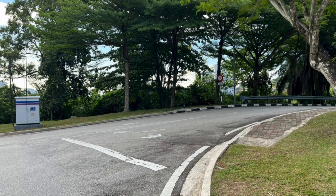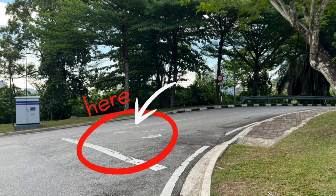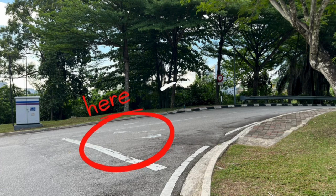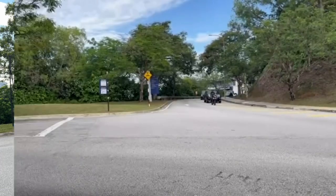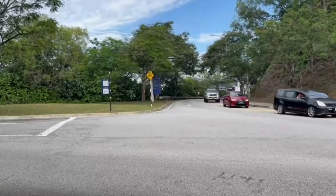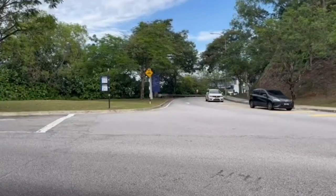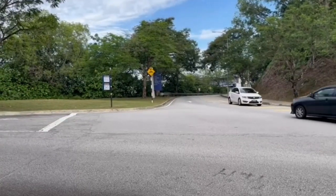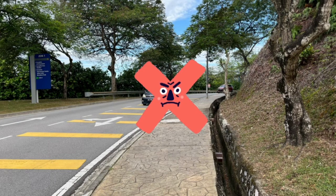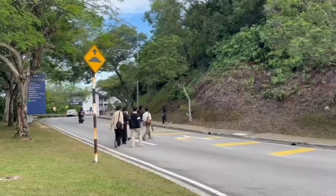Geometry layout. We move on to the next element in road safety audit, that is geometry layout. From our observation, there are no painted islands on the minor road to guide the vehicles to turn left or right. Then, the west approach only has one lane per direction with no dedicated turning lanes. This could cause conflicts, especially when one vehicle is waiting to turn while the others are stuck behind. Then, there are no marked pedestrian crossings or sidewalks, creating potential risks for pedestrians moving around the intersection area.